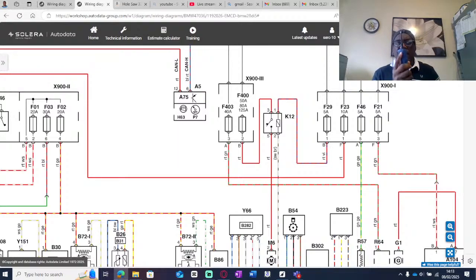So when you are testing a fuse with a power probe, I don't even look at the number. Now that I'm used to the sound, I just listen to the sound. Both sides should sound the same. That's the trick about using this tool. If they sound the same, your fuse is good. All right? I would say 99% your fuse is good. I know what I'm talking about there. I'll come back and explain that.